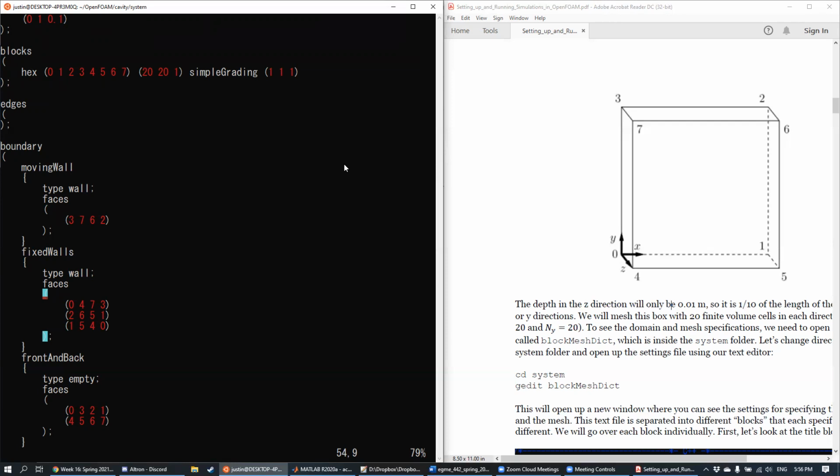In our MATLAB codes, we kind of took this for granted, because the way we applied boundary conditions is we used values of i and j and then looped them over our system. But for this case, we have to be a little more explicit about how we name our surfaces. So what we're going to do is create what are called named surfaces, surfaces defined with indices that we can refer to later in the code.